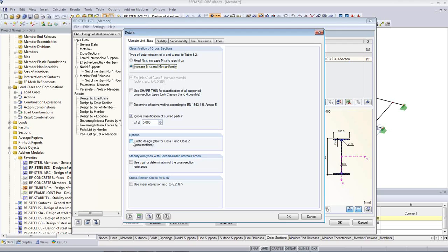For example, I-beams or I-cross sections are tackled really well, and you can analyze them for bending about major and minor axes, including axial force. If you have an angle, for example, then there is no solution for lateral torsional buckling with two directions of bending moments. In that case, the equivalent member method in Eurocode doesn't provide a solution for it.